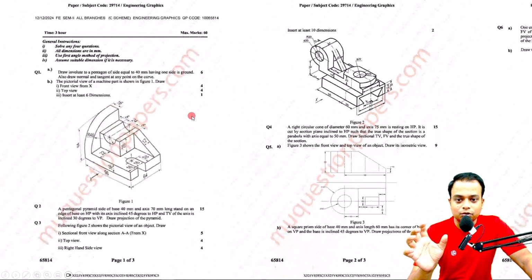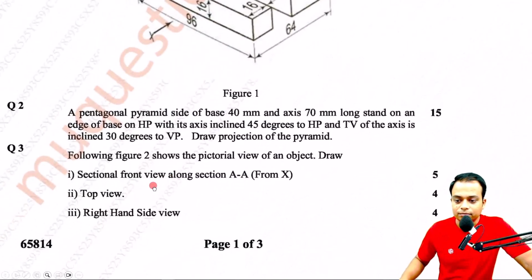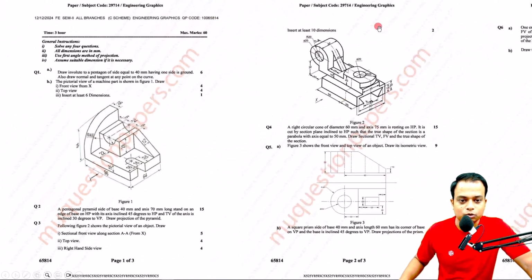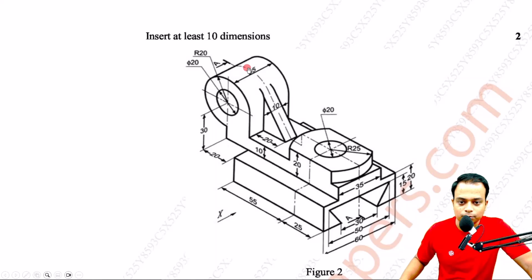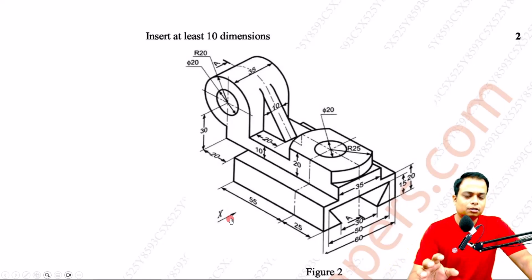In this case, you have to create the SFV, viewing it from the direction X along this section A. Let me show this to you. This is section AA. Please watch the cursor. This way, then this way, and we are done. So that's section A. You have to view it from X, and on this viewing, you have to create the sectional front view.